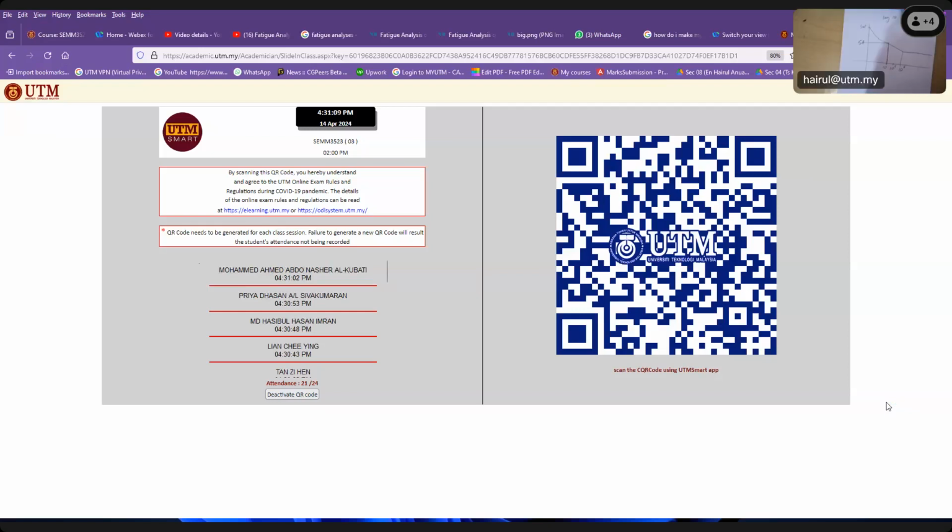The other part focuses on the notch. Remember, the notch is to the left of pulley A. Be careful. At the notch we don't have torsional stress. Study the solution. On the left is the groove, with no torsional stress, because torsional stress only acts right after the pulley.